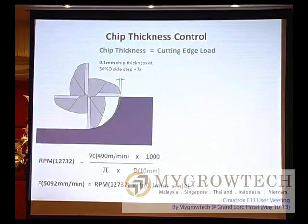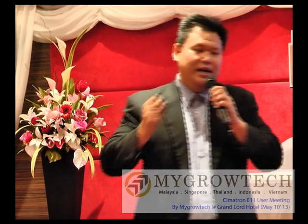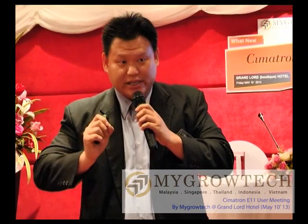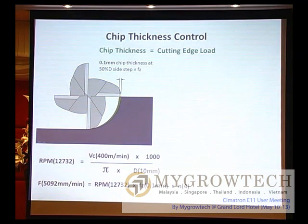Thank you. Okay. If you say it is the FZ, you might be correct if your cutting step over is 50%. If your side step is 50%, yes, the chip thickness, the green one, is the chip. The thickness of the chip is equal to FZ.